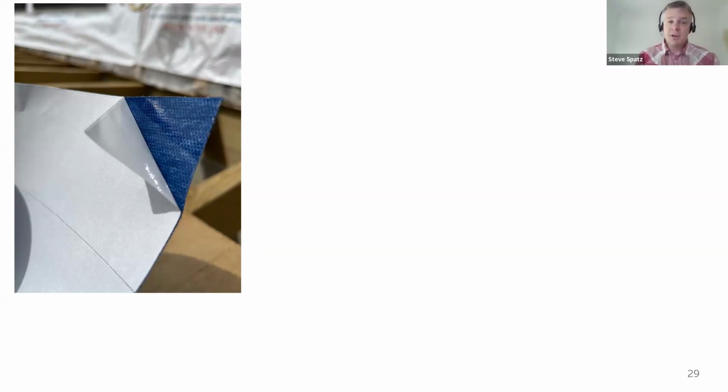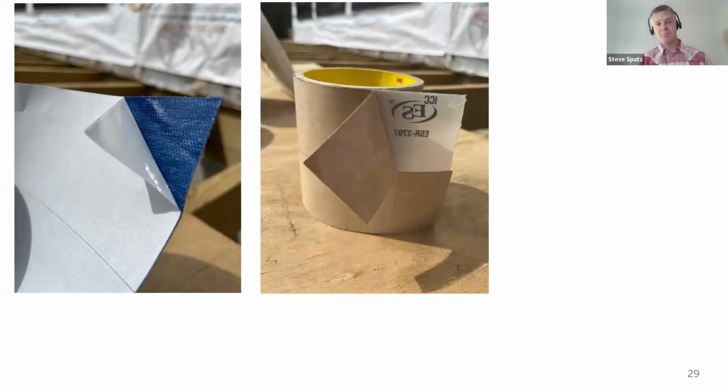And it's not just the pressure sensitive tape and the adhesive piece of it that's critical, but also the backing and the material that the adhesive is bonded to. So there's definitely a difference in behavior and critically permeability. There's that term again. So vapor permeability of the tapes that you're using to create an air barrier is definitely a consideration to be aware of.